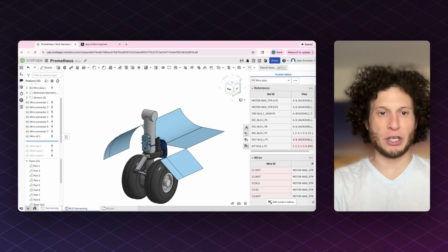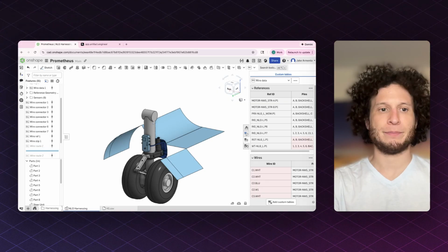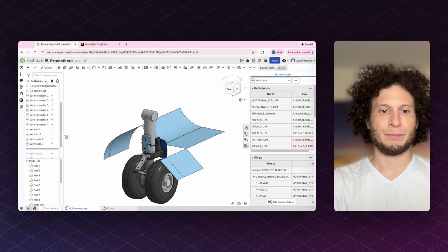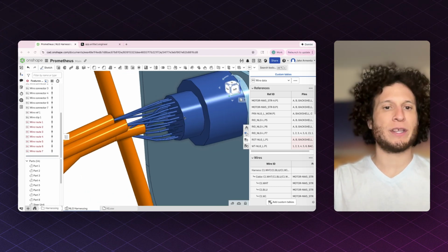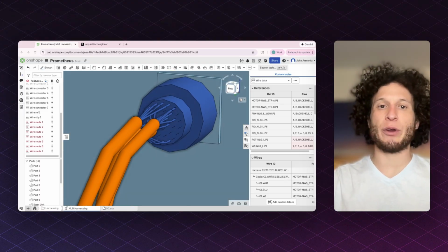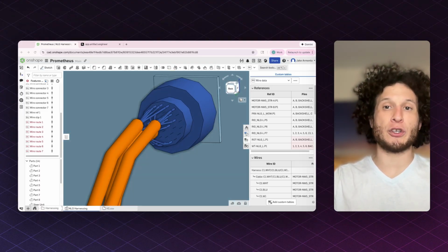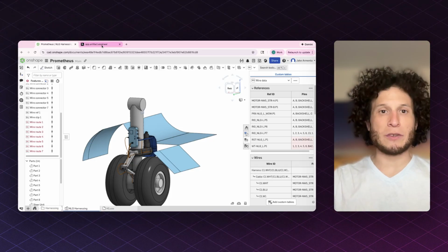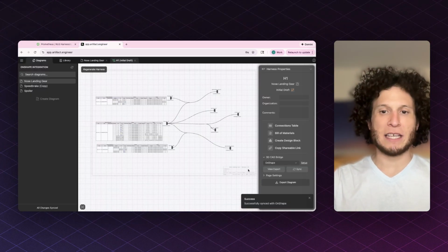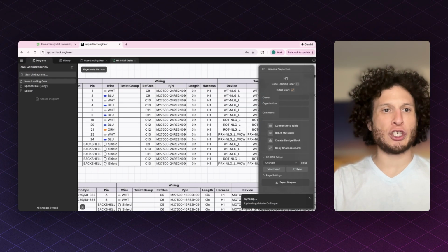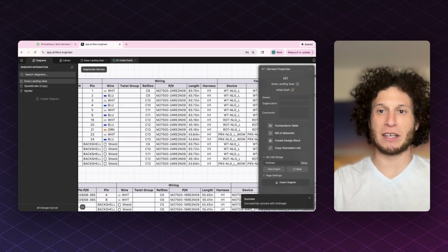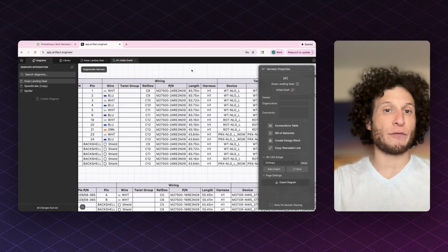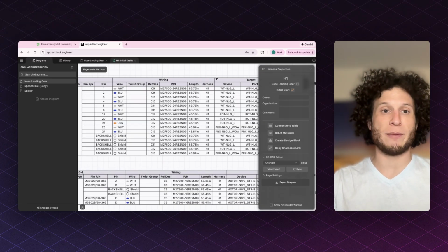Next, we simply route each wire or cable in 3D. Notice how, when routed, each cable displays an accurate outer diameter for both the wires and the bundle as defined in our library parts. Once I get the routes laid out, I flip back over into Artifact and I hit Sync again. This triggers Artifact to go back into the same Onshape doc, extract the lengths, and assign them to the cables and wires in our Artifact harness. We now see the exact lengths down to the fraction of an inch populated in our connection table.